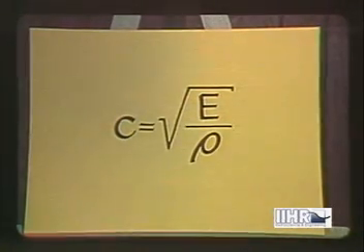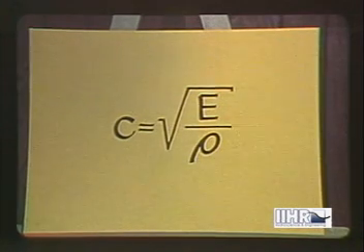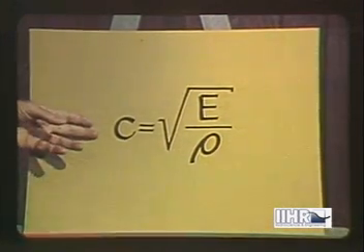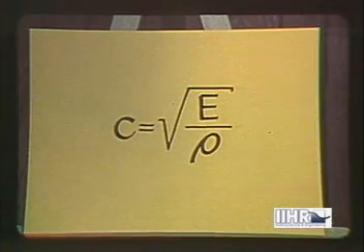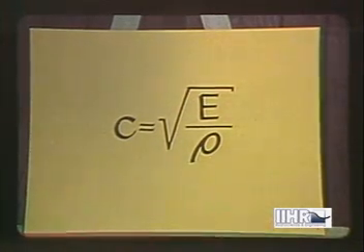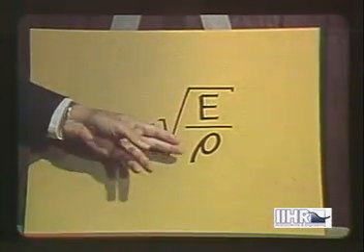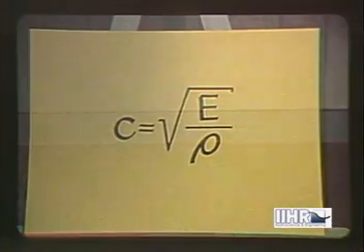produce a density change that is propagated elastically from the point of generation with the speed of sound. This speed, which we will call the elastic wave celerity, depends solely upon the elastic modulus and the density of the fluid under consideration. As you will recall from the study of elementary physics, there is a great deal of similarity between waves of different types. In fluid motion in particular, a close analogy exists between gravity waves occurring at the surface of a liquid and elastic waves occurring within either liquid or gaseous media.